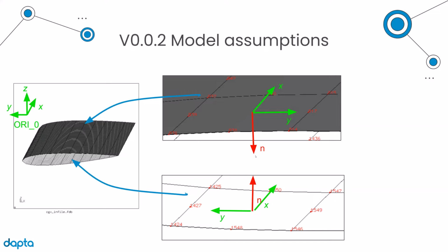However, if that's not the case, if we actually want to have different materials or shell sections on the top and the bottom, which is often what you do, you might have a joint here at the leading edge and a joint at the trailing edge. Then we might want to actually have two different surfaces, because the problem here is that if we have a continuous surface, we cannot actually induce that bend twist coupling that I was talking about last time.